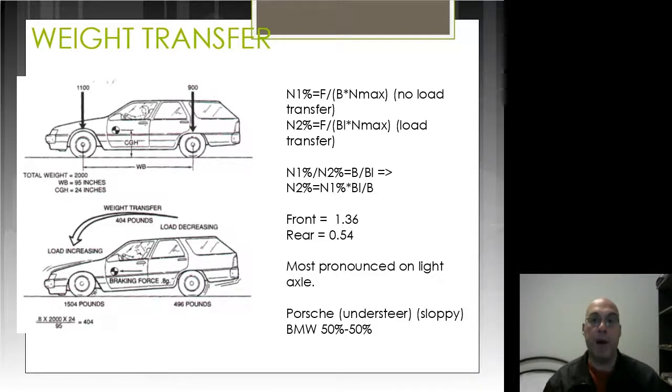But Porsches have a big problem because the front axle is light when you get on the power mid-corner. So when you get on the power mid-corner, you better be sure that the car has settled into a neutral or oversteer situation, because it will understeer if you're cornering close to the limits for the Porsche 911 or these cars with the engines hung over the rear of the wheel. So that will cause the car to understeer mid-corner.